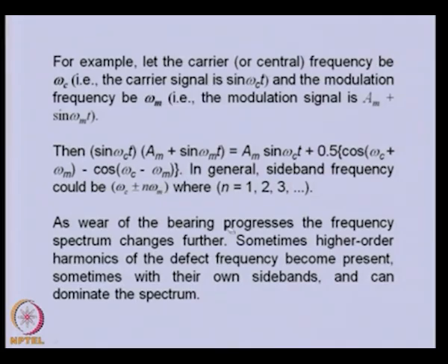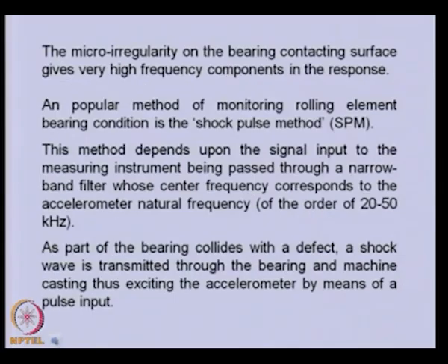As the wear of the bearing progresses, the frequency spectrum changes further. Sometimes higher order harmonics of the defect frequency become present, sometimes with their own sidebands, and can dominate the spectrum. So, even a high frequency component can be there in the bearing fault. The micro irregularity of the bearing contacting surface gives a very high frequency component in the response.